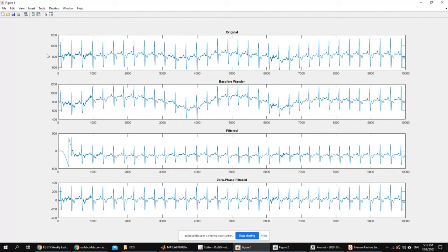So before you just blindly subtract the two signals and try to estimate the error, you have to look at the two signals and take care of these slight things. For example here, you probably want to remove the DC value. You just subtract the average of this, so that when you compare it to the outcome of the filter, it makes sense. Otherwise it won't make sense.